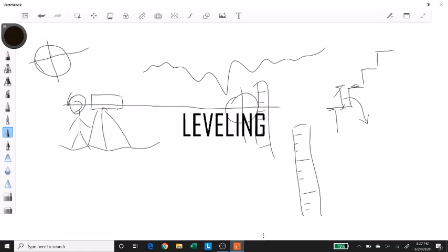Now, when you look through it on the leveling staff, although the graduations are very small, since it magnifies your vision, you get an enlarged view of these graduations. So what you would be looking at is a reading. If your crosshair gives you this, and if this is 4 and this is 3 meters, you'll be reading a value.